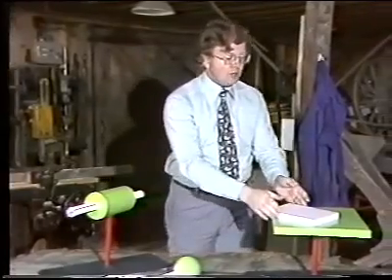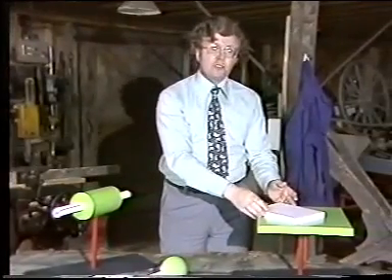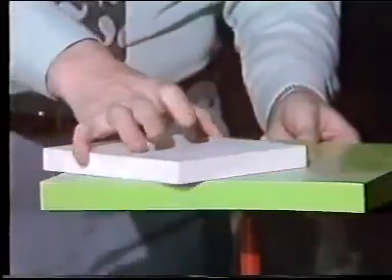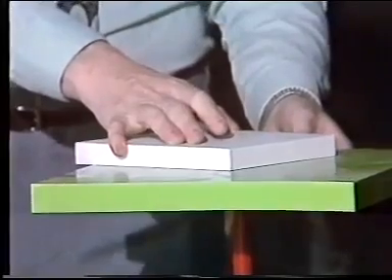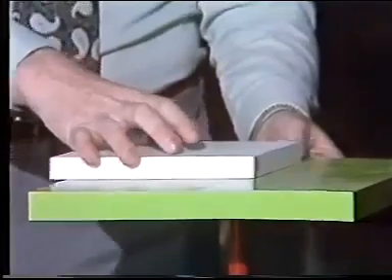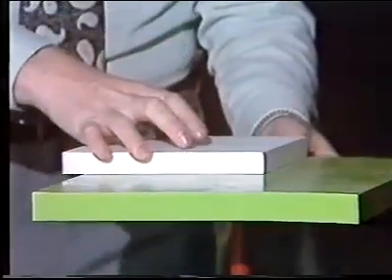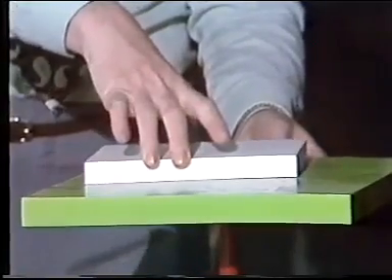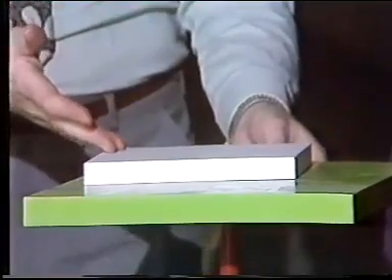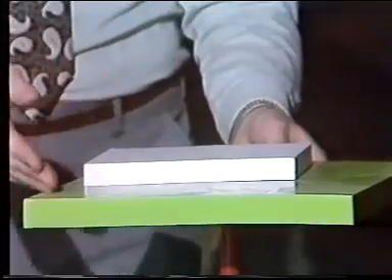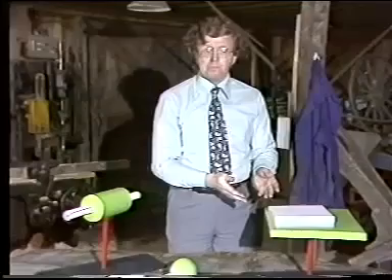And finally, we've got the planar pair. This joint isn't used all that much because of the difficulty of controlling it. One link has complete freedom to slide anywhere over the other. And you can think of this as a combination of 2 prismatic pairs, one sliding that way and one sliding that way, and 1 revolute pair turning about a vertical axis. Again, there's 3 different motions, and therefore we've got 3 parameters needed to specify the position of one link relative to the other, 3 degrees of freedom.